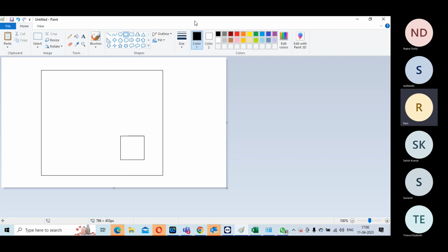Clock pull means early clock. Early clock means there's a buffer here, there's a buffer here, and instead of this one, the endpoint is connected. Clock pull means you will add one stage before. It's only a net connection. You can do that. Clock push is not possible, because you have to add one more buffer.